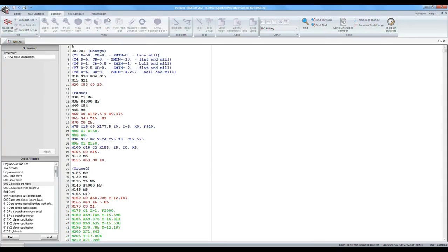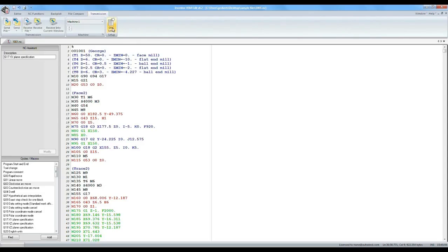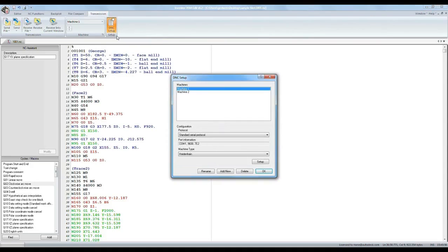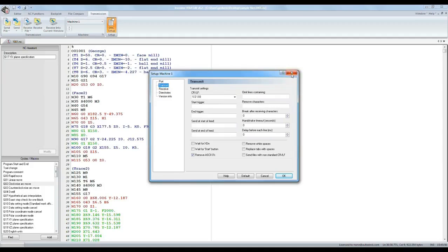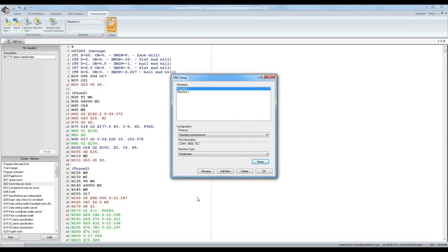And another thing that is built into this Inventor HSM Edit program is a DNC. So this is a drip feed or direct numerical control, and this can be easily set up by just going into these tabs here. This is used to drip feed the DNC file to older machines which don't have storage which can store, say, more than 1,000 lines.